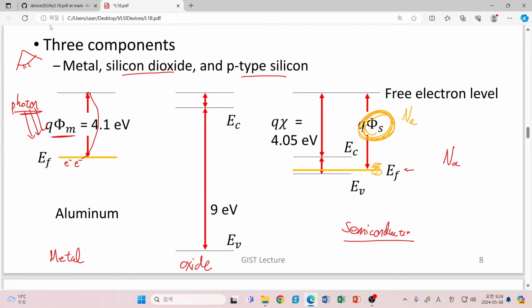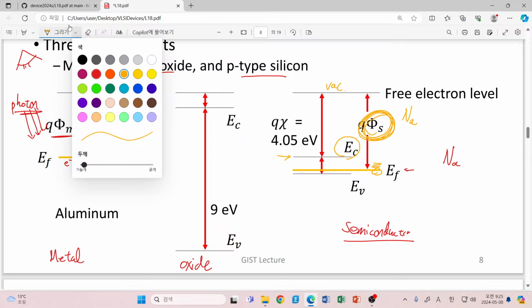So instead of the quantity corresponding to this one, we want to consider another quantity which is really assigned to a single material. What we can certainly say is, yes, the distance between its conduction band and the vacuum level. In this case, whether you have a highly doped region or a lowly doped region does not change the energetic location of your conduction band. So this is a more well-defined quantity.